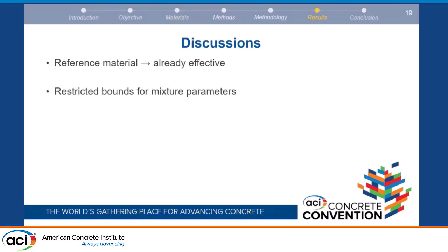We restricted the parameter boundaries of the optimization after an initial iteration because the neural networks had too much trouble predicting too far from the design of experiments region. But now that the predictions are better in a lower cement content region, we are progressively extending the experimental region, as was done in iterations 4 and 5.